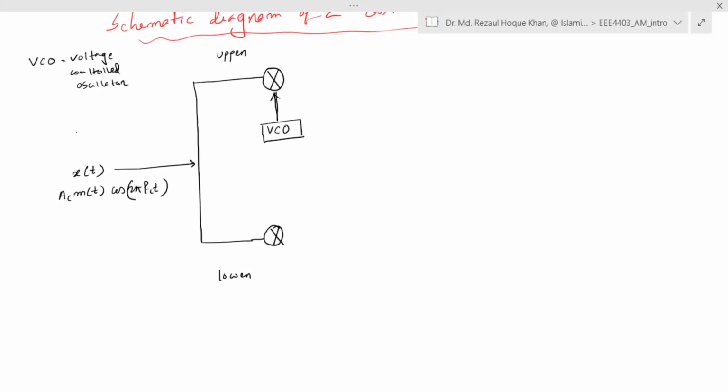So each of the demodulators is fed by a VCO. With which frequency? With the locally generated carrier, which in our case is cos 2 pi fc t plus this offset phi that we actually saw in our non-coherent demodulation. This phi is introduced, right? Okay.